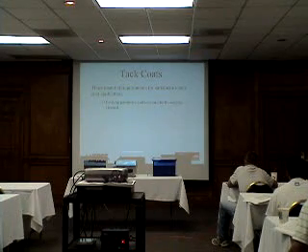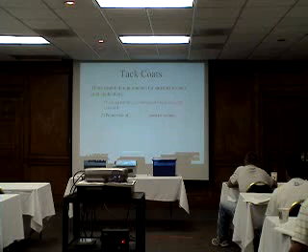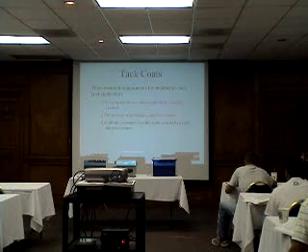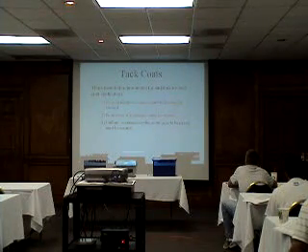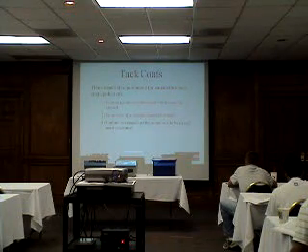And eventually, that's going to break loose and you'll wind up with a big old pothole. We need to make sure that we've got the proper application, and again, uniform coverage over the entire area that we're going to pave. I think I'm wearing it out, but it's very, very important that uniform coverage be obtained.